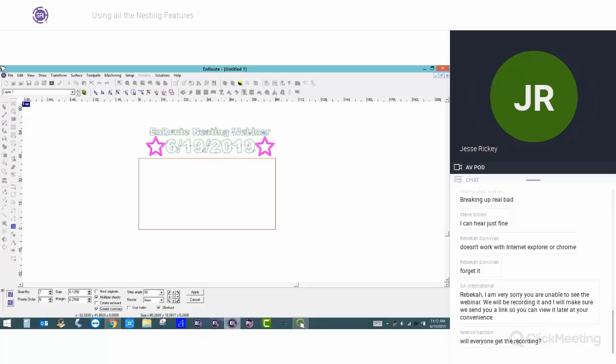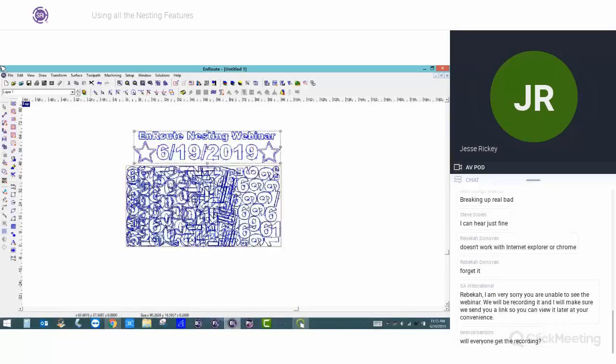Okay, but I do want to create a summary on this one because I want to see what parts are on what sheet and how well it nested it. I'm going to say go ahead and apply this. We're using the same step angle and I'm still using the new nester. So I'm going to wait for the progress bar in the bottom right hand corner to go all the way over to the right. It is creating multiple sheets and doing quite a bit of math, so it may take just a few minutes to process. As you can see, it's kind of moving along on its own pace.